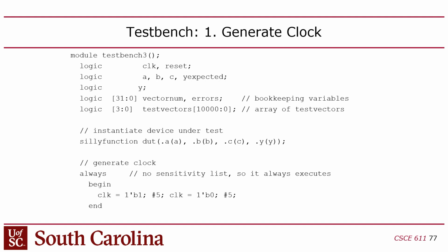This is an array of vectors, an array of multi-bit logic signals, right? But this syntax is really obnoxious because remember how I mentioned earlier that when you make an array, a multi-bit signal, you have to put the numbers before the name, which is unlike any other programming language array syntax, right?